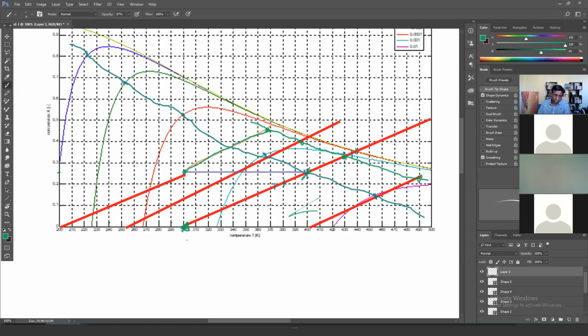It's different here in the PFR. You are entering at 300 Kelvin and a conversion of around 0.25. But as you move up this line, you will find all those points in your PFR, right? So if you look 1 centimeter into your PFR, you will find a point here with that conversion, and so on. So you will be able to observe all these points in that PFR. And in a way, this introduces a new consideration. With the CSTR, it was kind of straightforward. We just wanted the whole CSTR to operate at that nice reaction rate.